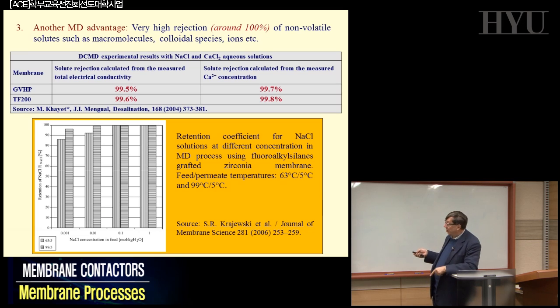Why? We learn now. It's because the membranes utilized here, commercial membranes, don't have a sharp pore size distribution. The 100% is only if all the pores are around 0.1, 0.2. All these membranes are far away from having this kind of result. That's why you have this small deviation from the expected value, but still quite competitive with most real membranes. Also in RO, when they tell you 99.5, when you go to measure, it's 98.5 or 99.1. These are all 99.7, 99.8, etc. So quite interesting as a value.